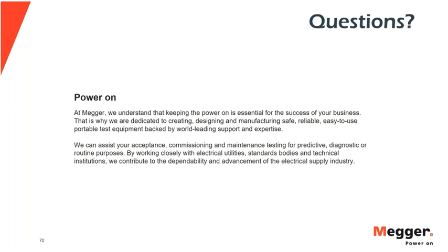And so the temperature correction, which can only be done on a case-by-case basis, would depend on what the transformer is, how aged it is, what its condition is. But the whole point in figuring out that individual temperature correction for that transformer would be to know exactly what the power factor would be if I waited for it to cool down to 20 degrees C, without actually waiting for it to cool down to 20 degrees C.